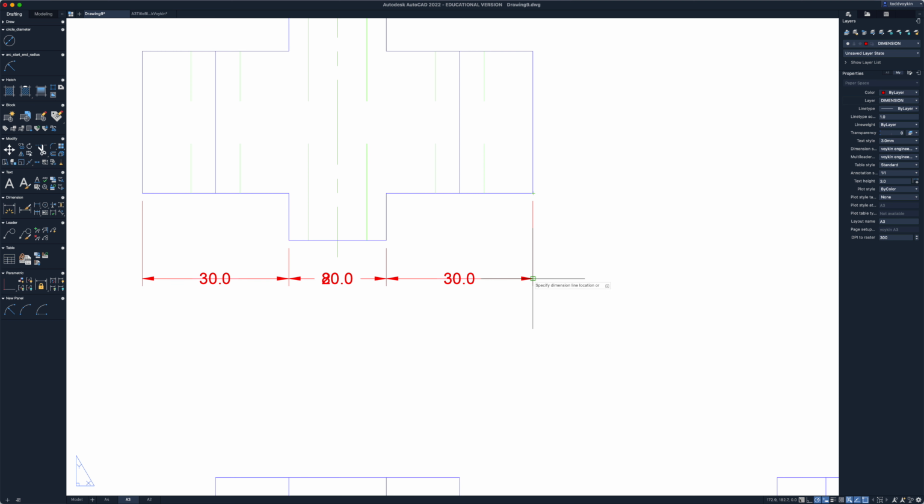And the problem is I want to come from that point down 8. So when I say that, it's the English that you want to listen to. I'm coming from this point down this direction. So I'm actually just going to type in from, and where, this point, and which direction, down, and then type in 8 and enter, and that will set that point at 8 millimeters from the last dimension.